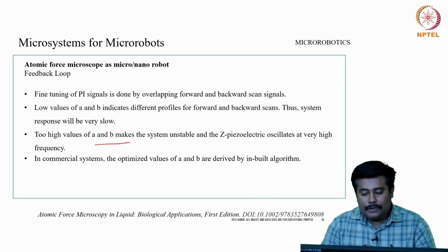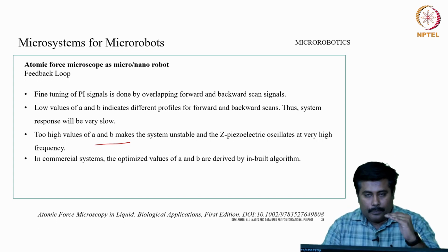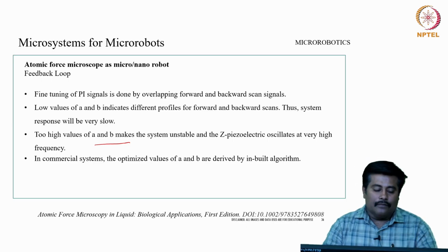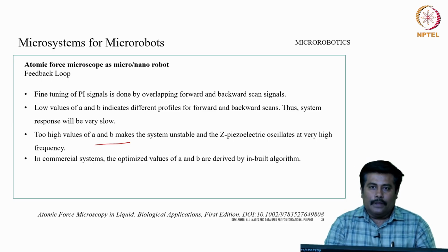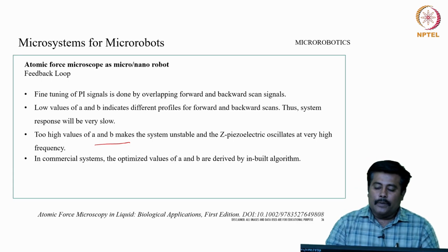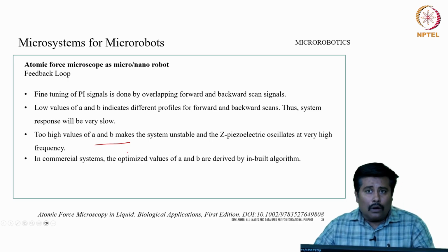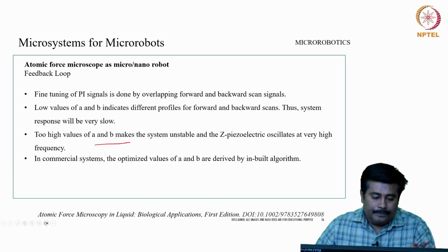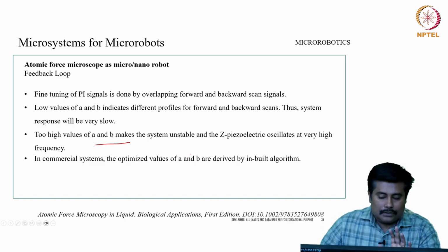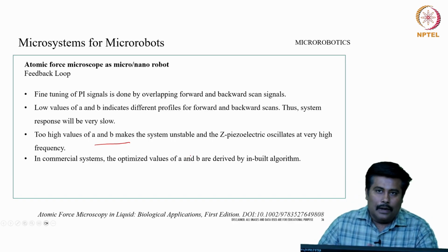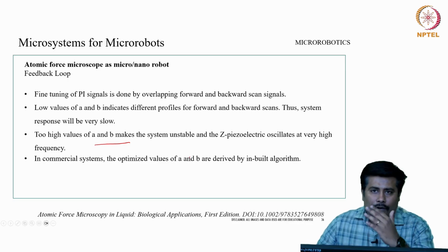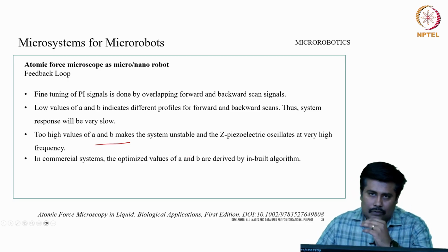The Z piezoelectric system oscillates at a very high frequency. In a commercial system, the optimized values of A and B are derived by an inbuilt algorithm, which takes care of the overall compensation within the arrangement. So, these are some of the key aspects with reference to AFM as a micro and nano robot. It is a fundamental where AFM characterization is used.